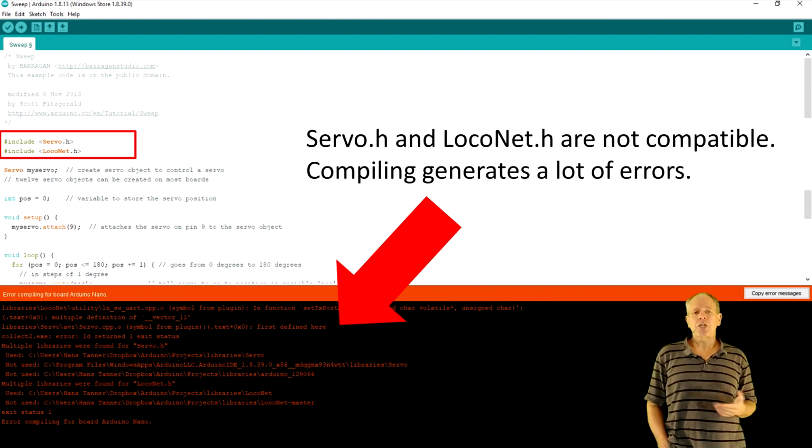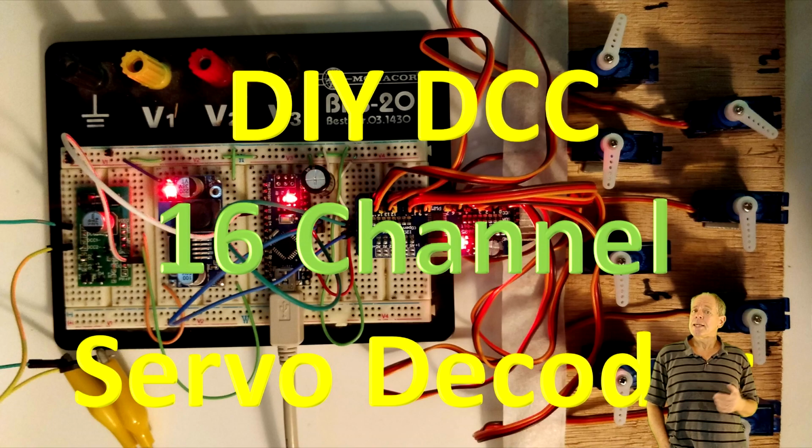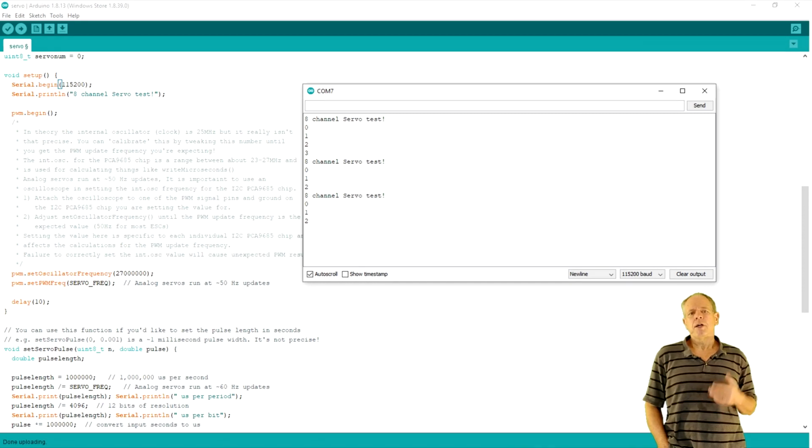Instead, I simply changed my approach and used the PCA9685 module to drive this servo. It is kind of overkill, as this module can drive up to 16 servos, but it works reliably, as I have seen when making the 16-channel servo decoder back in video number 17. The PCA9685 module is connected to analog ports 4 and 5, which are the predefined I2C pins of the Nano. To drive it, we can use the Adafruit servo library, which can be installed using the Arduino IDE.